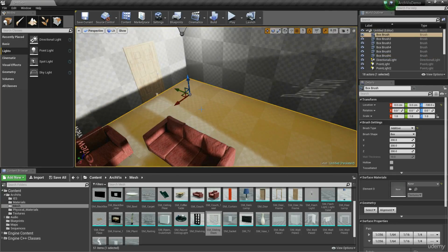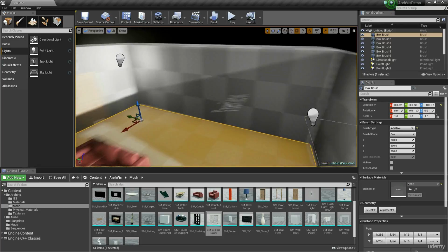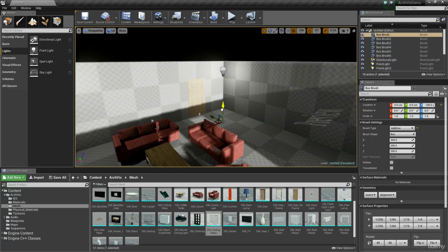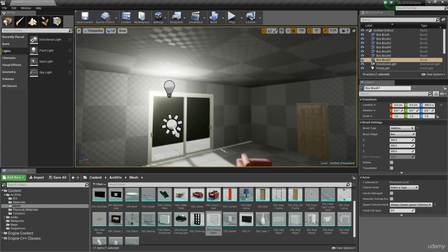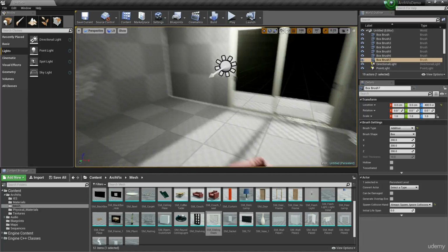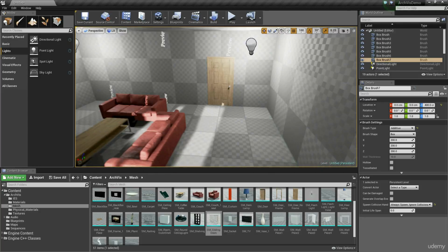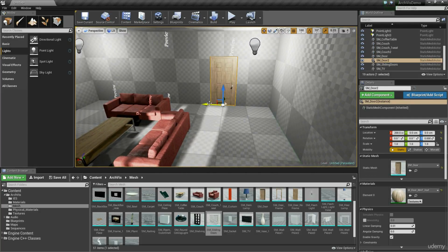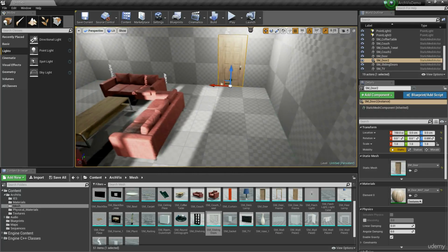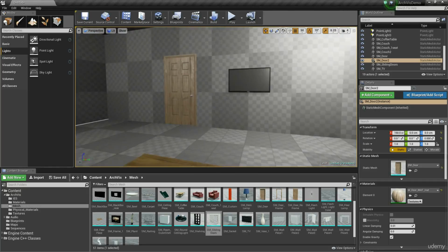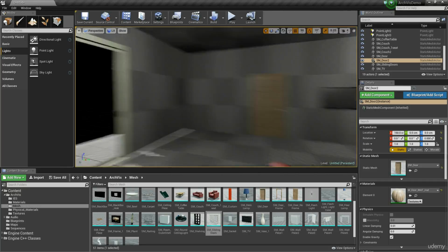So it's at this point that I am going to go ahead and create a roof so I can get a better idea of how this is going to be looking. I'm going to set my snap grid to 100. I'm going to alt drag upwards. And you'll see that that's nicely snapped to the roof because we stayed on the grid. And we've got this going on, which looks okay. Thinking I'm going to go to a 50 centimeter snap grid and move this across as well, actually. Just give them a little bit more space as they kind of come in that door. Cool. So with that in mind, let's start looking at what we can do to kind of make this room a little bit more interesting.